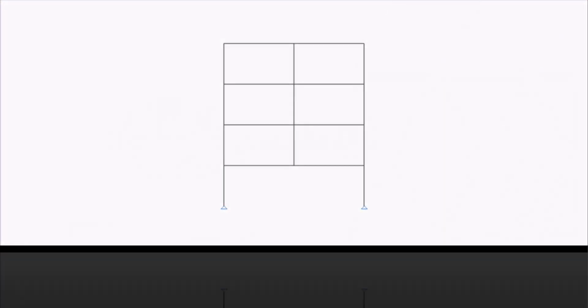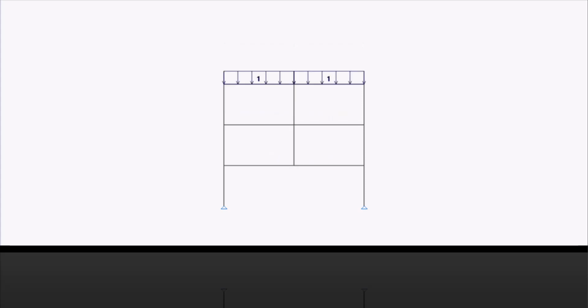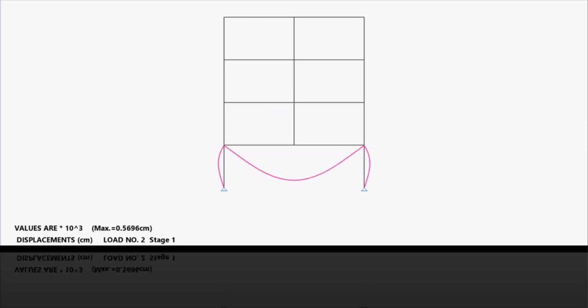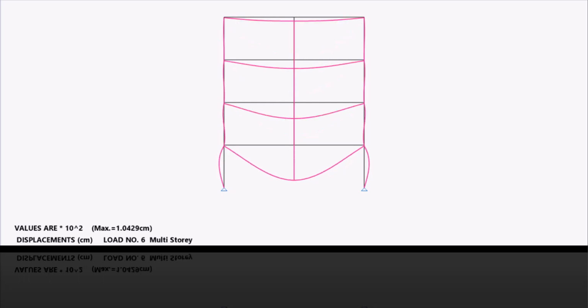Hello everyone! This video demonstrates how to divide models into construction stages and explains about the multi-story feature in STRAP. Usually, a multi-story building made of reinforced concrete is built floor by floor, with each floor representing a new stage of construction. As a result, some of the construction loads imposed on a floor act without the presence of the floors above it during the construction, which affects the way forces are distributed in the building. For this reason, the multi-story feature has been added to STRAP.